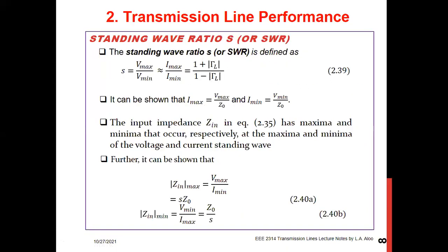From that expression, we notice that the points of maxima and minima will occur respectively at the maxima and minima of the voltage and current standing wave.